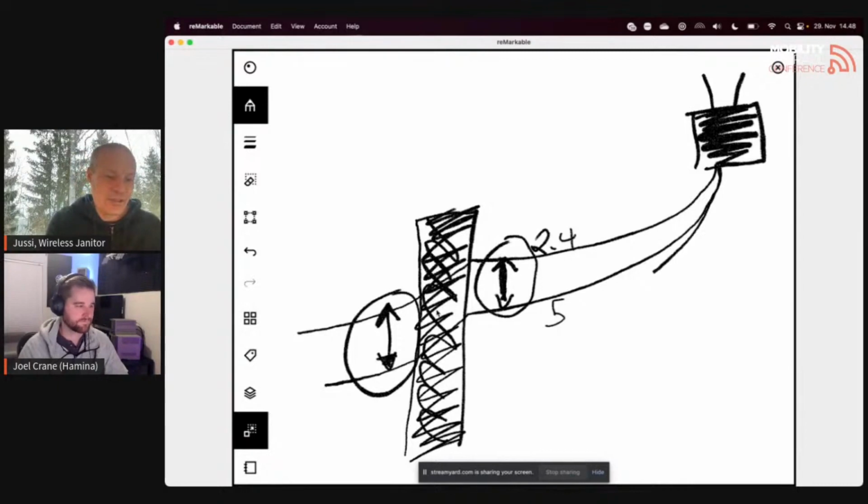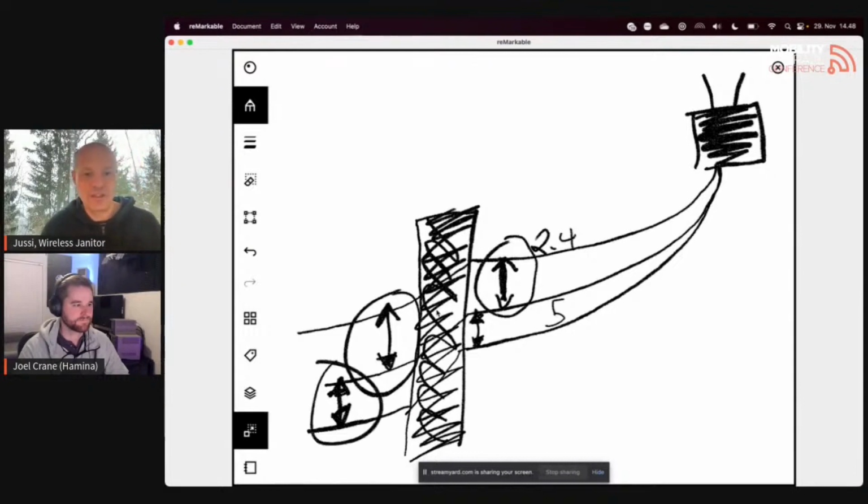And with 6 gigahertz, I'm just going to do this highly scientific drawing here. The free space difference, again, isn't that dramatic, but how much of a difference there is between 5 and 6 gigahertz when penetrating the walls, that's a good question, right? And that's wall material dependent. There is some difference in how 5 gigahertz signals are attenuated and how 6 gigahertz signals are attenuated when they go through walls, and that varies with the wall material type.